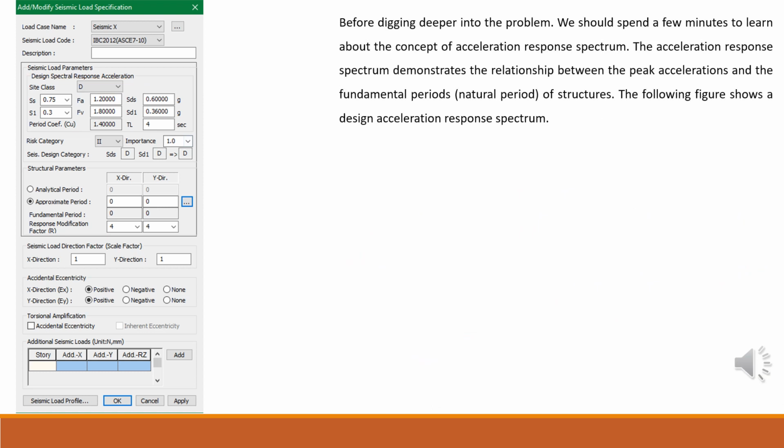Before digging deeper into the problem, we should spend a few minutes to learn about the concept of the acceleration response spectrum. The acceleration response spectrum demonstrates the relationship between the peak acceleration and the fundamental period, or natural period, of the structure. The following figure shows a design acceleration response spectrum.